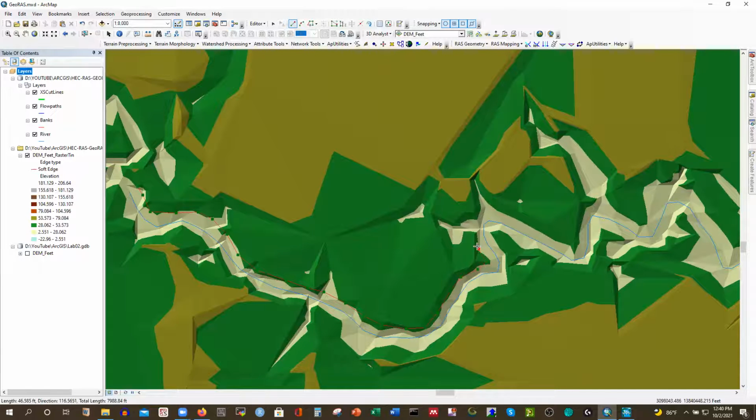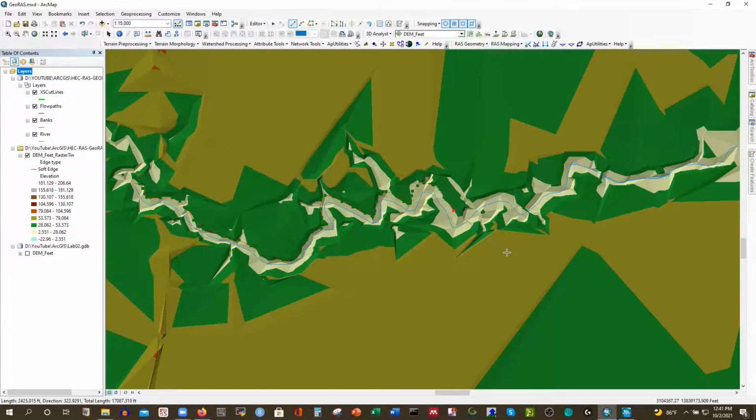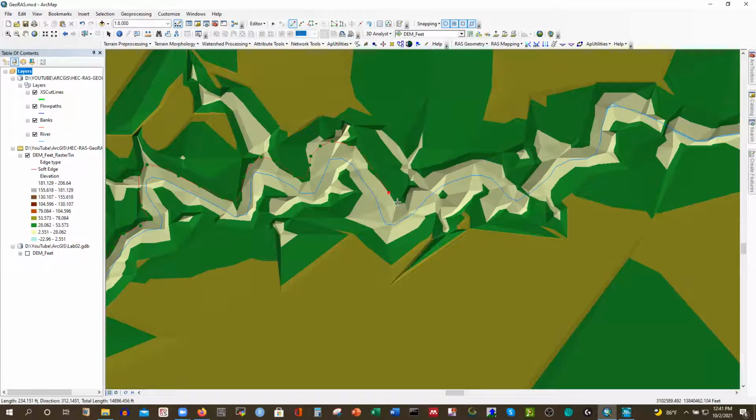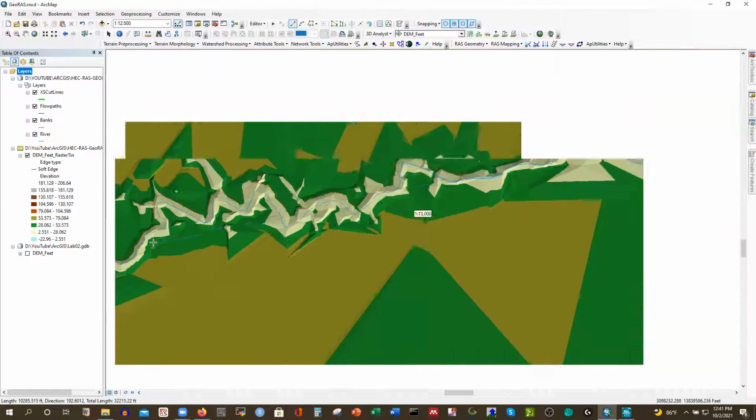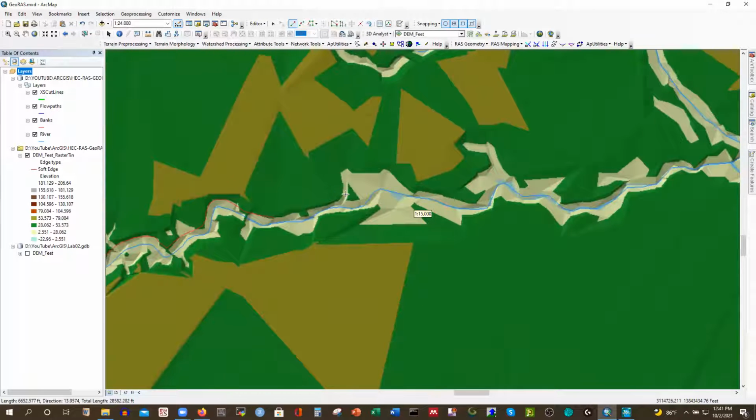And here it is. Just follow this white line, because that is the floodplain for sure. That's why we need to generate, because in the DEM data we can't even identify that. That's why we need the triangulated irregular network to identify our bed level or bathymetry data. To survey this length of a river will cost a lot. So we don't need that anymore, because people are trying to generate this topographic data set from different sources.